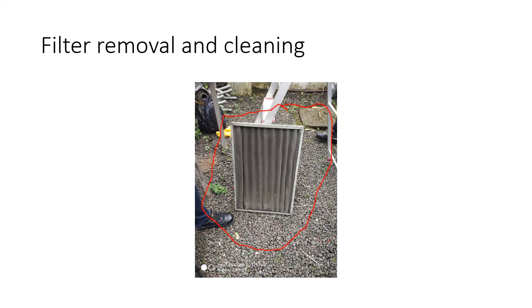The filter will improve your cooling efficiency and help maintain the shelter temperature as per the requirement. In every PM schedule of the OEM and the SP technician, filter cleaning is mandatory in all kinds of preventive maintenance.